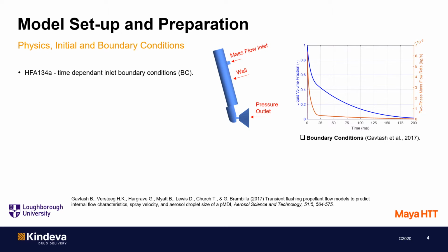The flow leaves the computational domain through the exit cone of the actuator nozzle, where the pressure is taken to be 1 bar. As I've stated before, we are particularly interested in the relative amounts of vapor and liquid in the actuator sump and their spatial distribution. The flow involves vapor and liquid phases, so it is necessary to use multi-phase flow capability. We have chosen STAR-CCM+ as the CFD platform and utilize the volume of fluid capability because this algorithm has the important capability to represent flash evaporation, which is responsible for the development of the vapor phase.